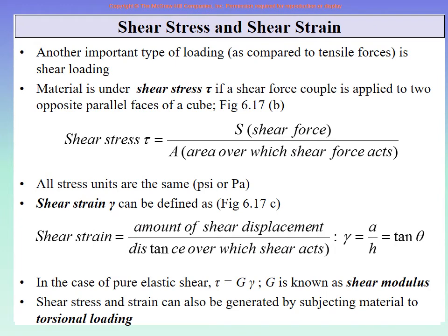With this, we have now done the normal stress and strain. Remember from your statics course, you have forces in the normal direction, then you have shear forces and torsional forces and so on. Normal means tensile or compressive: along the axis, there is a surface, and the load is at 90 degrees to the surface, so it is a normal load.